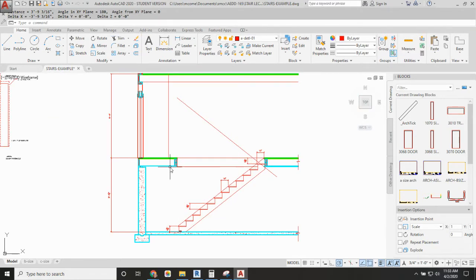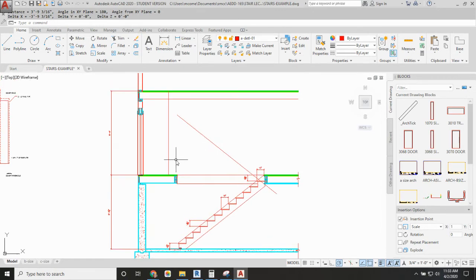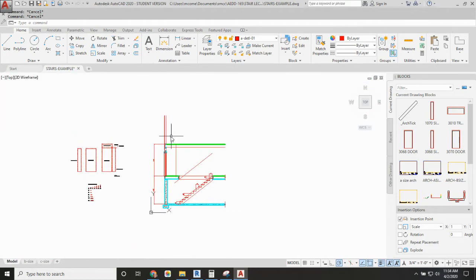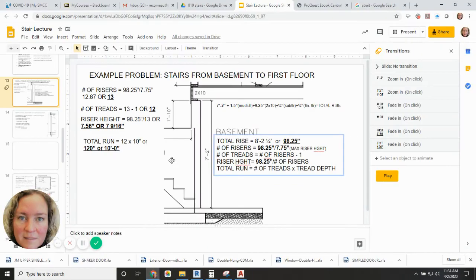And on the first floor, I might want to go up the stairs coming through the front door. The stairs often are located right in front of you in a lot of traditional homes. So the stairs are usually stacked on top of each other because then they all automatically create natural head height in the space. So let's get rid of that. Well, actually, let's mirror that also. There. So if we build the stairs here, I'm going to make sure I have my lines set up correctly this time. We go back to the stair lesson.